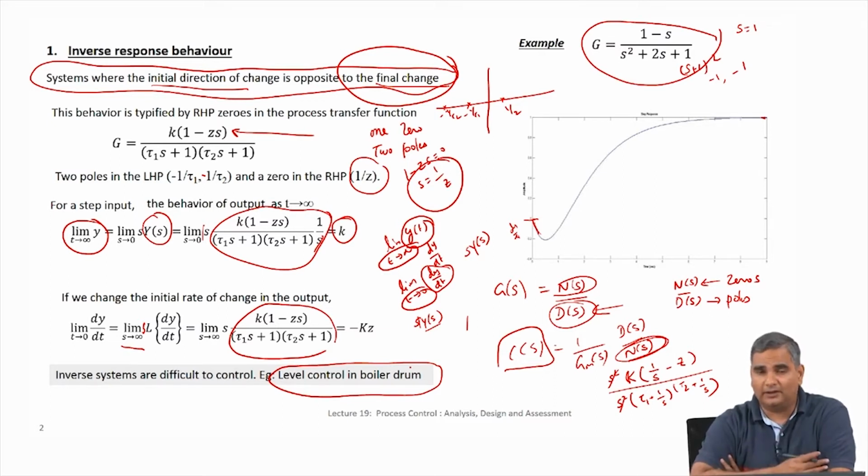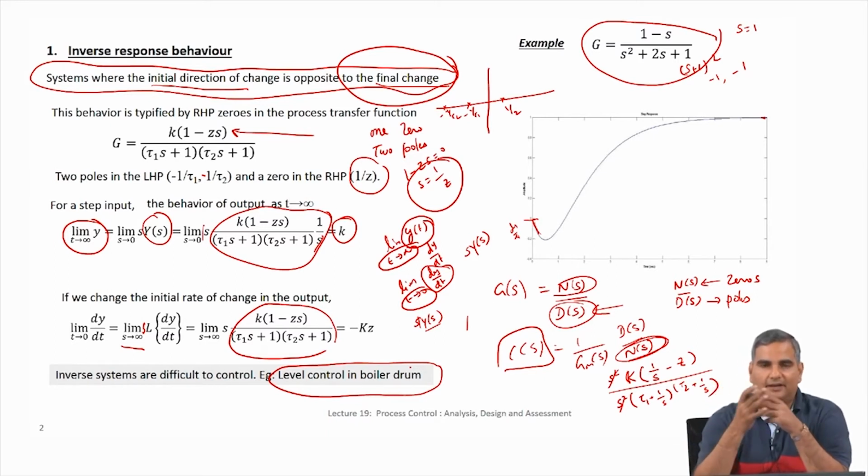So, basically what it says is, if you have a desired response that you want, till now, whatever the desired response was, I could design a controller based on it by using the formula for the direct synthesis controller. But now for the first time, if I have a model which has a right half plane 0, then when I want to design a controller and I know what I want, so I give you a G desired, and if I am not willing to make any compromise and say this is the G desired and you have to design a controller for this, then if you go ahead and design the controller based on this G desired, your controller will become unstable.